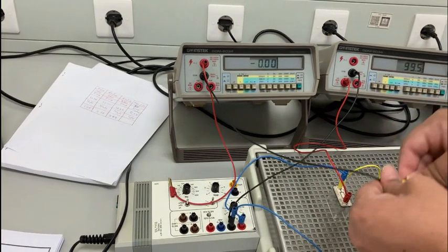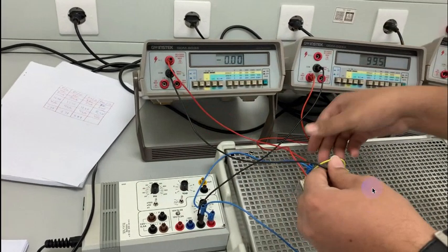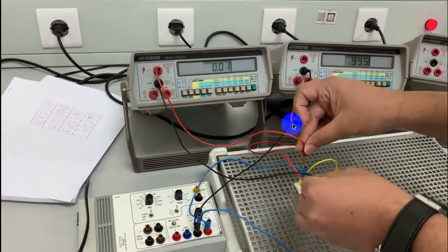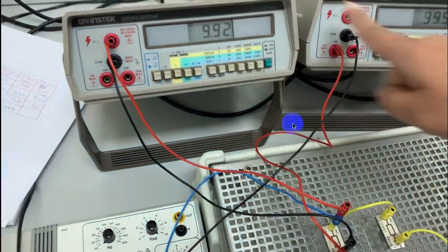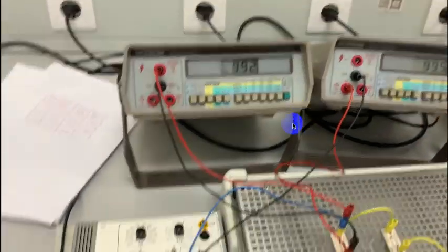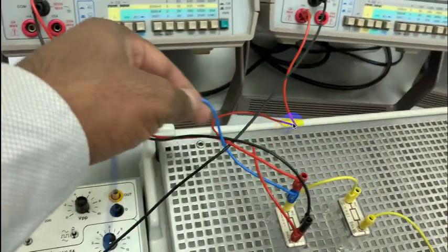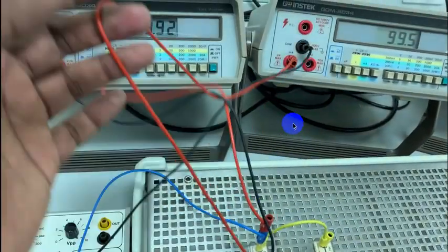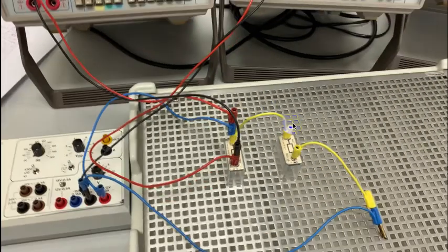So how much was I total? It was around 120, and I1 is 99.5 because the resistance value here is 100. So let us see the voltage again, to verify the voltage is the same. The voltage is the same because voltage will not change when it is connected in parallel. Just make sure of the connections. The connections are perfectly fine.